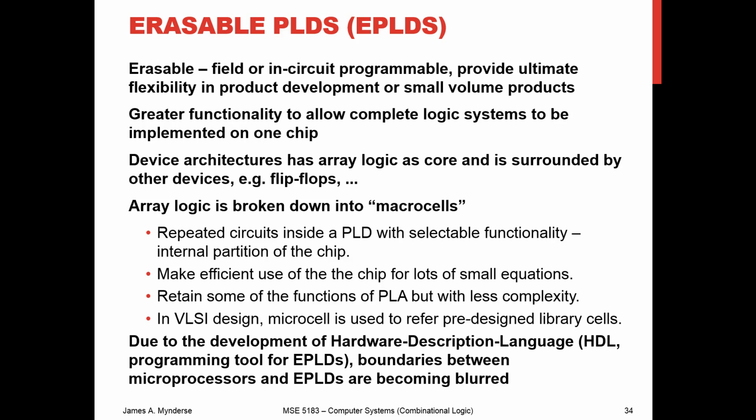The problem here is that it's going to be programmed using something called hardware description language, HDL or VHDL, which is not necessarily a widely known skill. And anymore, when you look at FPGAs and microprocessors, there's sort of this blurring of all these together, which is part of why we went away from EPLDs in terms of this class. But it is something that's out there still. It's useful. It's going to implement your logic. It's going to implement it very fast. It's going to implement it relatively efficiently, and it's reprogrammable in the field, which is great.